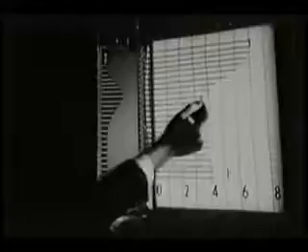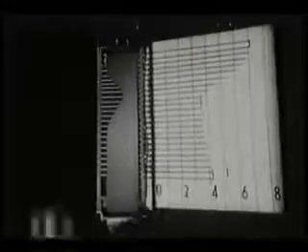For instance, the area divergence here is much too rapid, and there is very little static pressure recovery in the diffuser. Far less than before. Even a very small amount of viscosity, if it leads to boundary layer separation, can produce very large changes from a truly non-viscous situation.